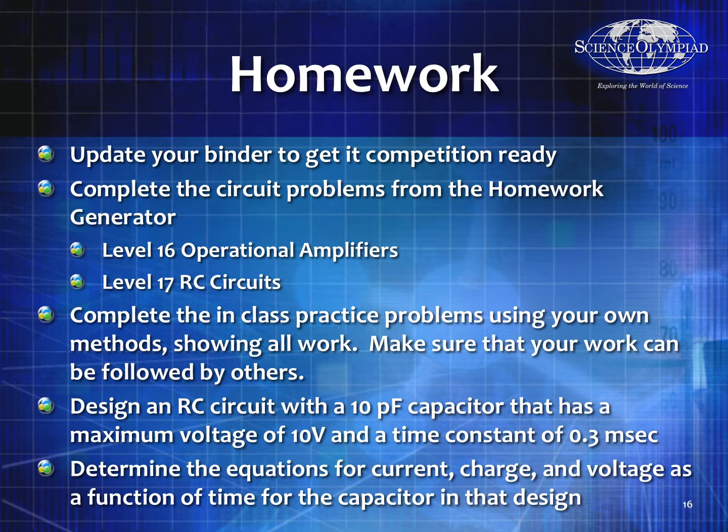So again, update your binder, do your circuit problems from the homework generator, do level 16 operational amplifiers and level 17 RC circuits. Make sure you can do all of the in-class problems. I'd like you to design an RC circuit with a 10 picofarad capacitor that has a maximum voltage of 10 volts and a time constant of 0.3 milliseconds. Show all your work, and determine the equation for current, charge, and voltage as a function of time for the capacitor in that design. Thank you so much.